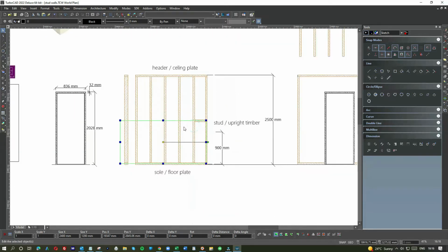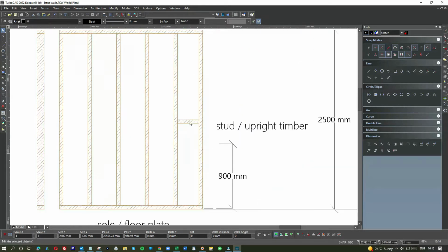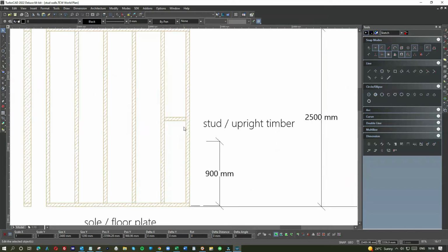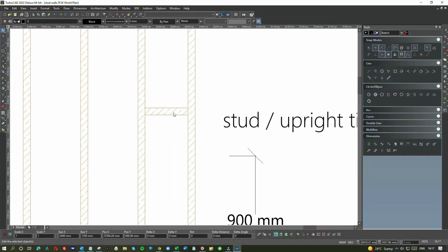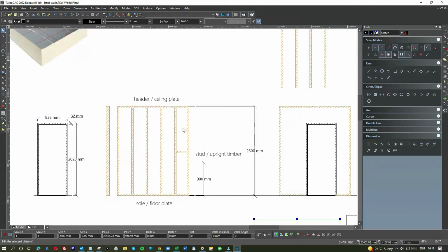So that's a bit of an explanation on the plasterboard, and the main reason for telling you is to tell you these noggins, they don't just go in anywhere, like 2 foot, 2.5, 3. They go in according to what it is you're covering the wall with, and mostly it's plasterboard. So therefore it's 900 if it's 900 plasterboard, or 1200 if it's 2.4. That's about it really on the noggins.